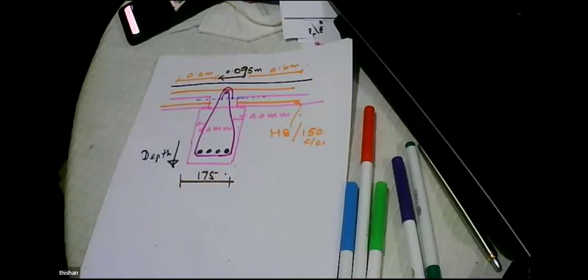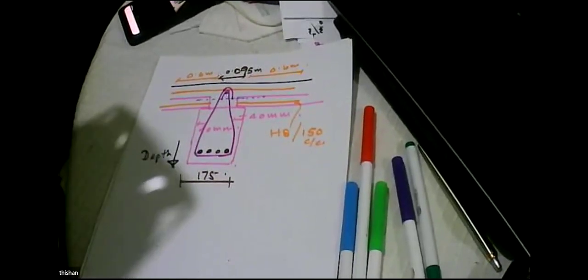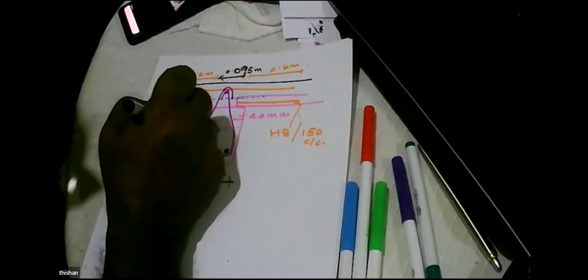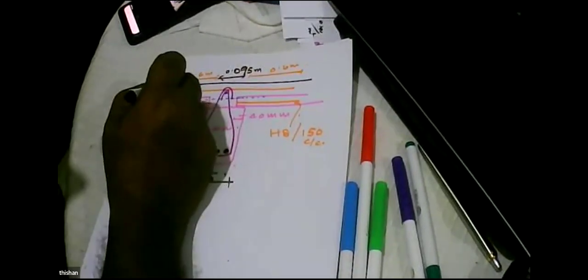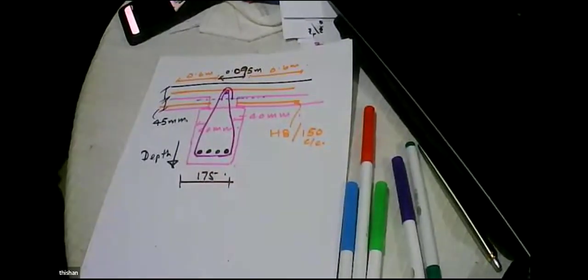Great. So, this is a slab system. Then, depending on the span, in a similar manner, considering it as a flanged beam, we can design the beam as well. That we'll discuss next day. But today I explained in detail how we arrived at 45 millimeters, why it is sufficient because the cover requirement is only 15, and why we had to use admixtures and go for high strength mix concrete when you are doing the precasting operation.